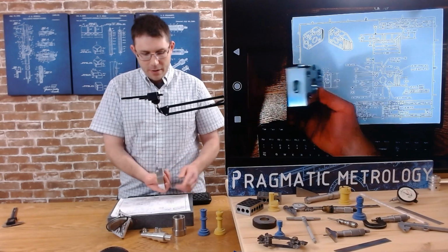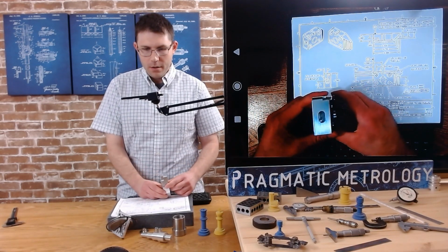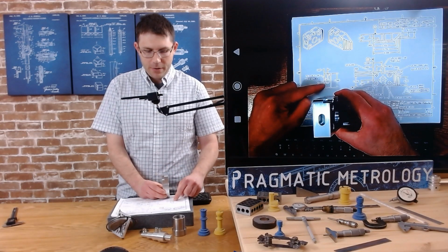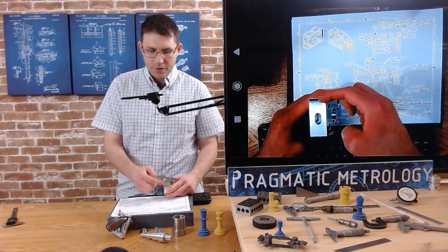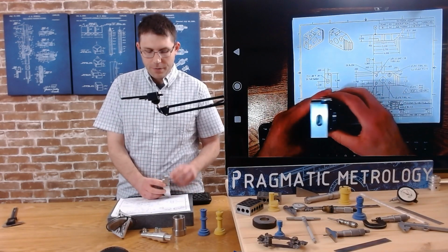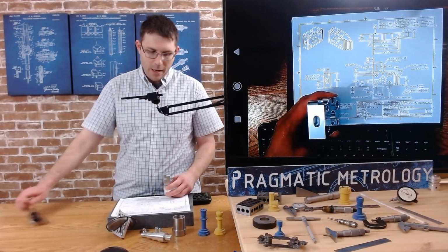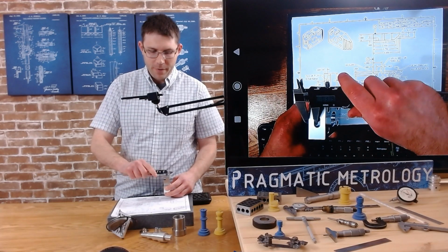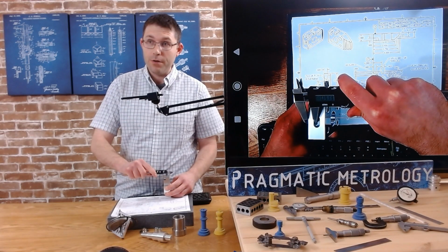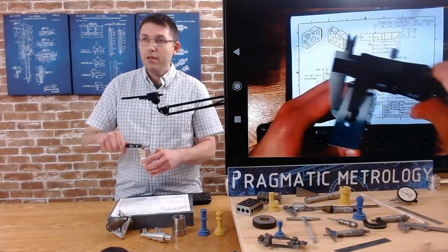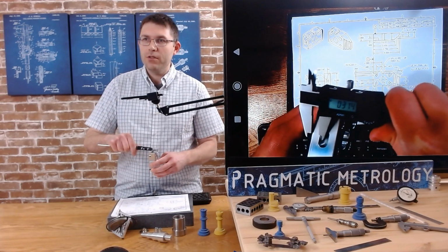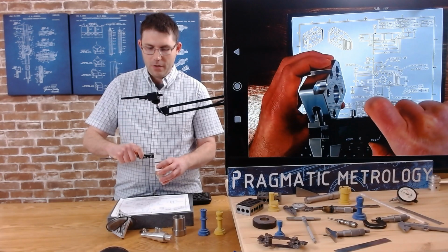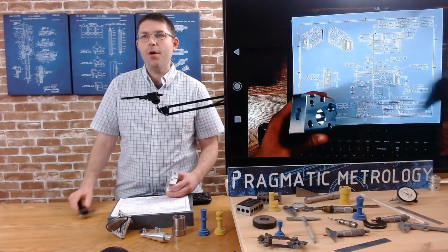I can see that this back face is this back face. This little notch here is this little notch here. So if I'm going to measure the slot, I'm going to grab it from that face and do 313. The slot edge is 313, 314 from that face, and then I can use half of the slot width to figure out where the center is.